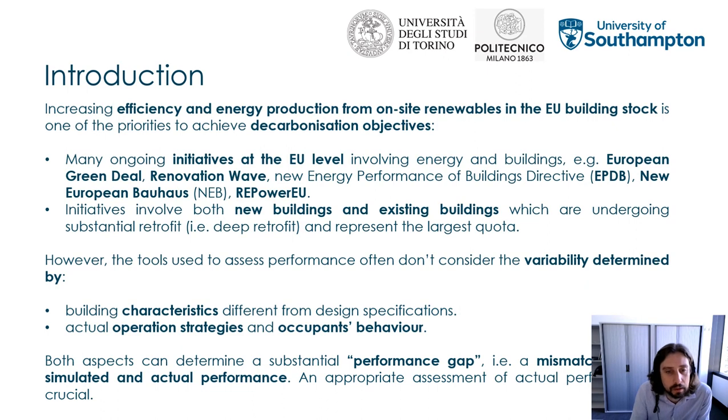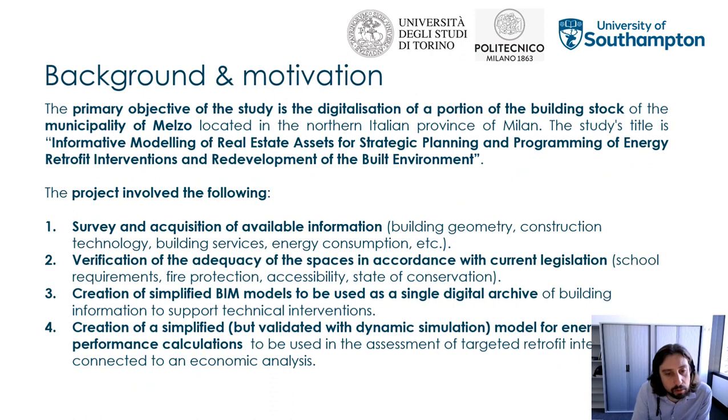So we need to design solutions that are quite effective in decarbonization. And unfortunately, for existing buildings, we have to be able to define a very good baseline model, able to capture the performance of the existing building. And this performance has variability that is determined by the intrinsic building characteristics, but also by the behavior of the people. This variability of performance can lead to a mismatch between the simulated and the measured performance, which is reported quite often in the literature with the term performance gap.